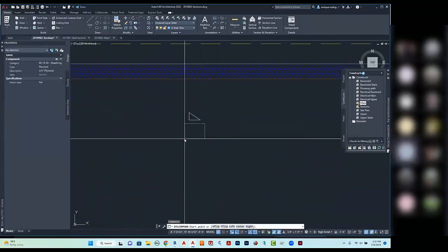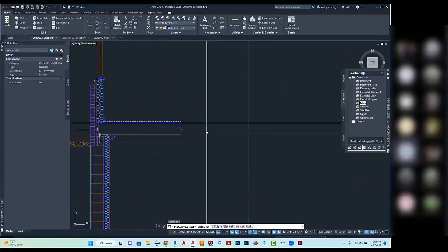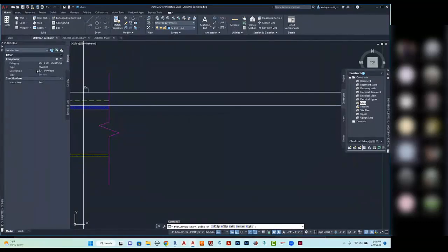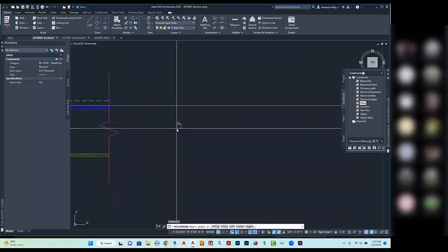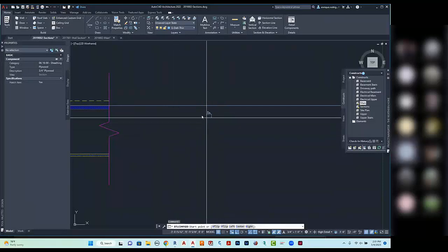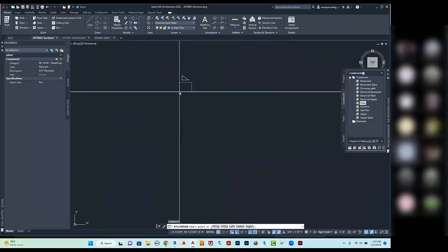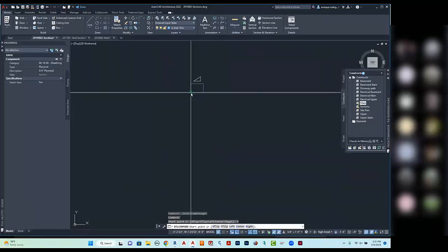When we insert the component, you will notice that you get a little item next to your cursor crosshairs. Also here under properties, you're going to see that it says description, 3/4 inch plywood. There's the sheathing, and it also tells you that the view that we are installing is a section. So we're going to go ahead, and if you notice, the plywood is going to occur above the line. We want it to occur below the line. So we're going to do a Y flip.